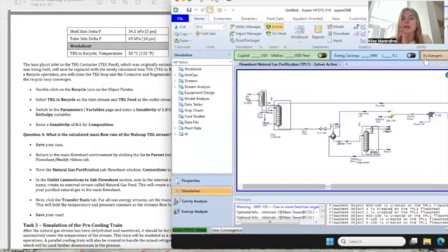So the issue that I was having was that I was stuck in hold, which sometimes can happen by accident. I must have clicked something, which is why my mixer wasn't converging and the flow was going backwards. So just double check that.